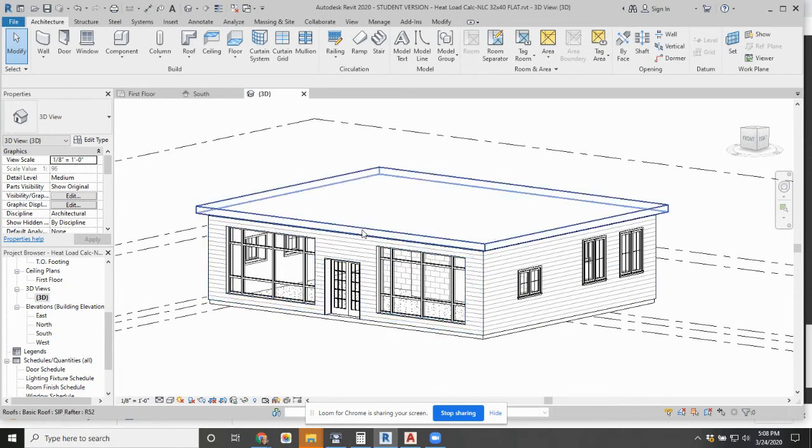So if we heighten the walls by 2 feet on this side and lower the walls by 2 feet on that side, we actually end up with the same wall square footage that we calculated to begin with. So doing things like that are some of the ways that you can kind of fiddle with the roof pitch and things to try to get this to work.